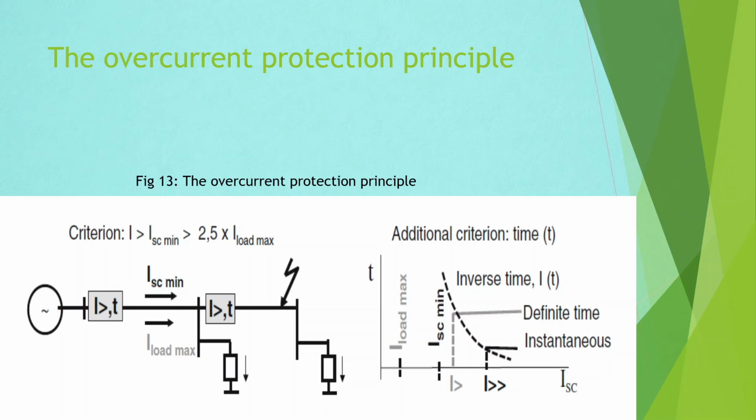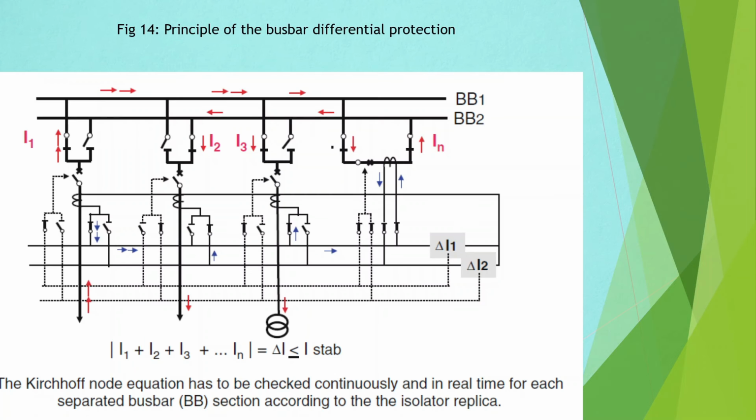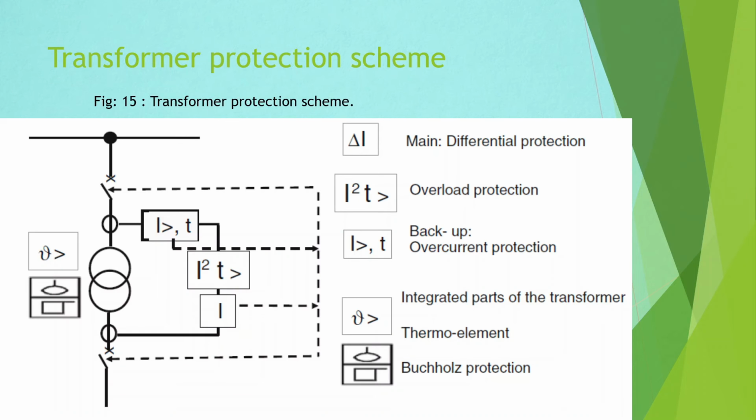Switch operations have to be performed as quickly as possible after the faulty busbar is tripped, for connecting the affected feeders to the healthy busbar segment. The busbar protection is configured as a system with digital bay units and one central IED, as shown here in the figure. Both components of the system are based on identical technology. Now let's understand the transformer protection scheme.